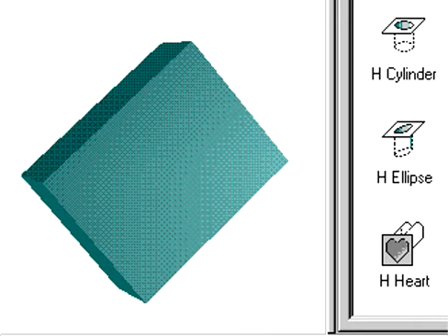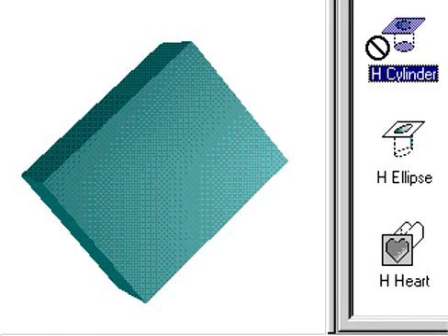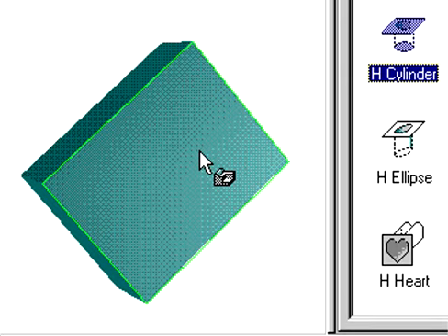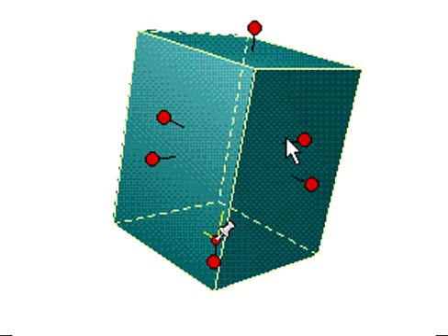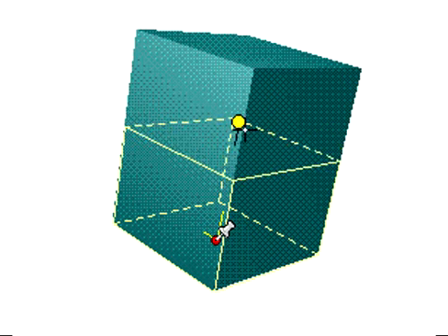You can remove material from your model with one of the many holes in the Shapes catalog. Holes work like other IntelliShapes. Drag one from the Shapes catalog and drop it on your model. When you select an IntelliShape, you see its shape handles. To make the shape bigger or smaller, drag one or more of the handles.